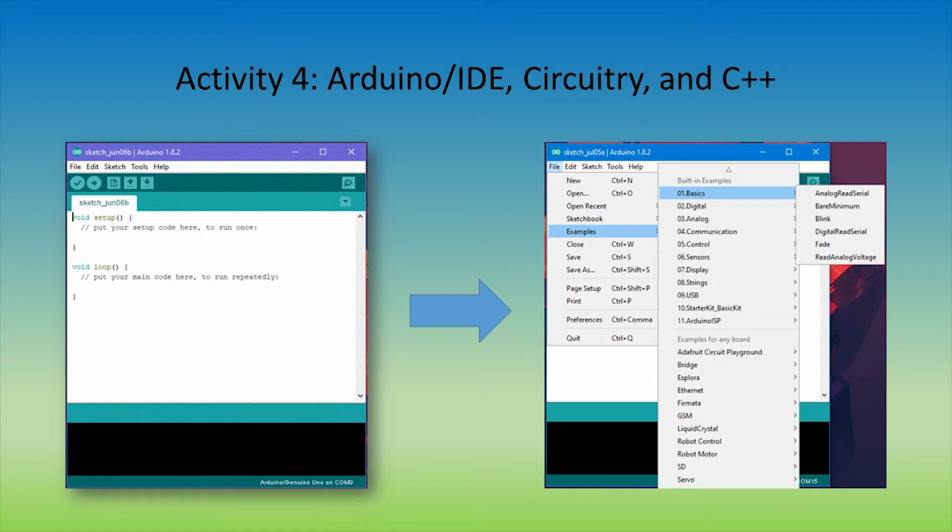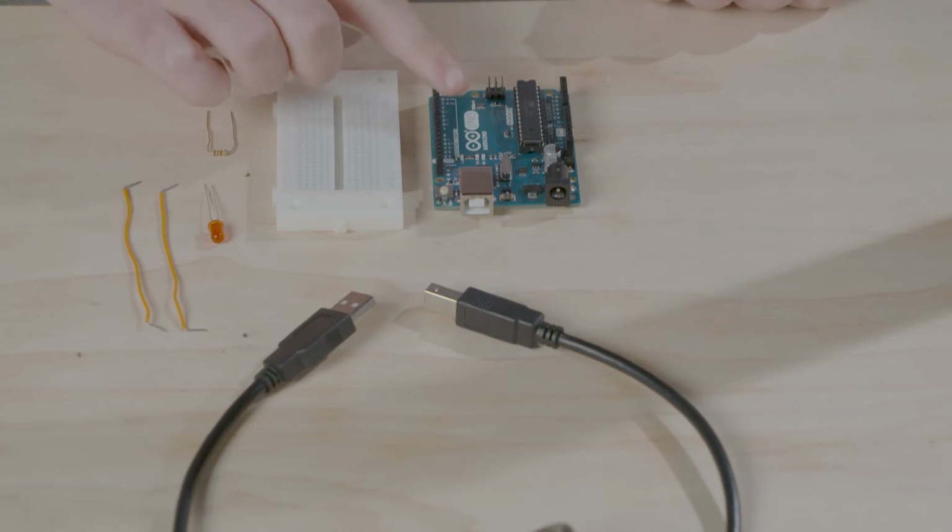Now you will begin a small activity that introduces you to coding an Arduino on its respective IDE. Start by connecting your Arduino to your laptop and running the IDE. Then go to File, Examples, Basics, and try out the codes named Blink and Fade. Read the description for each and experiment with them. A small challenge you could try is to alter the frequency of the flashing of the LEDs on each. We'll be using the Arduino and using the scripts Blink and Fade.